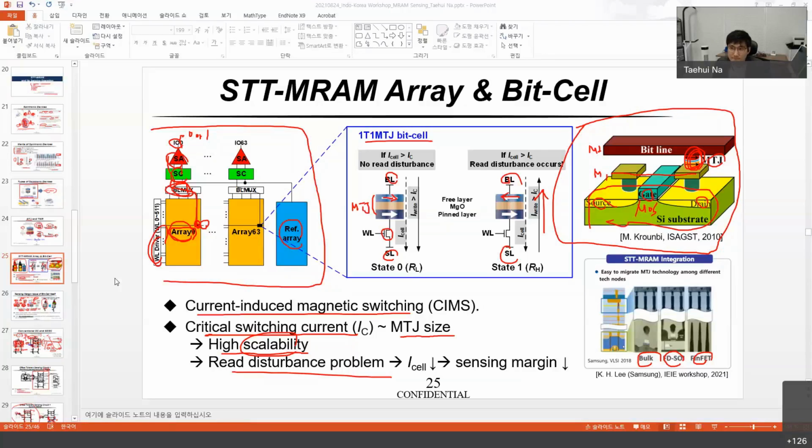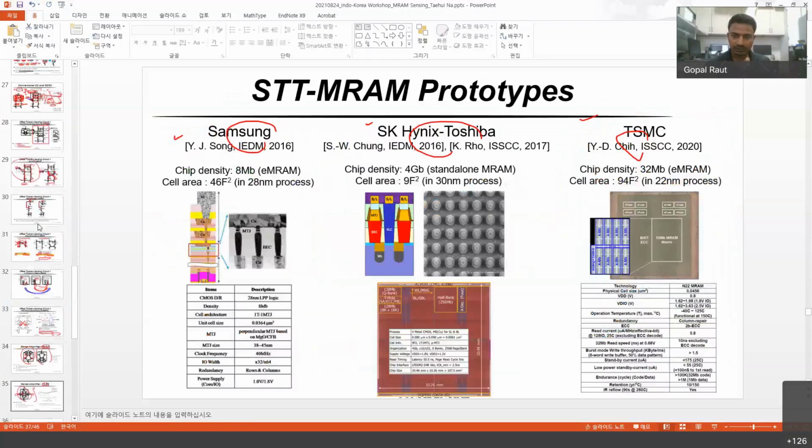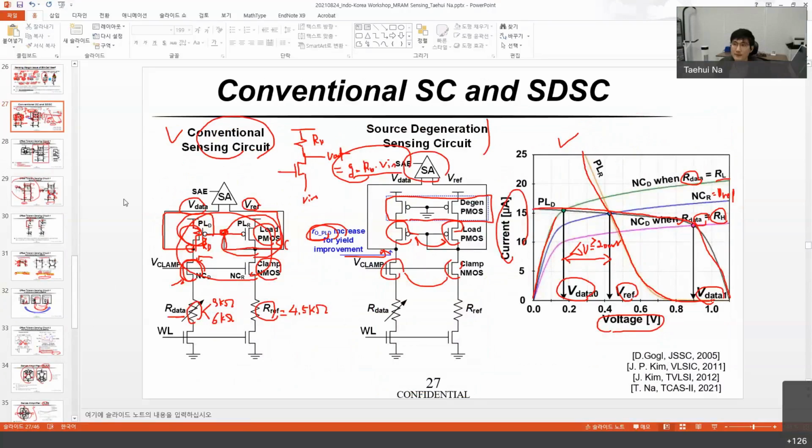And one more question, Professor. In slide number 27, if we see the VI characteristics as you mentioned over there. I think, yeah. So here, if we see that VI characteristics, the distance between the lines for RL, RH, and the supply resistance is nearly equal. So can we consider there is a linear effect of resistance, or is there any perception we should take from this VI characteristic? In MOS devices, the distance between the VI characteristics increases with the VGS value. But here the distance is quite similar. So is it the linear effect of resistance in the current?